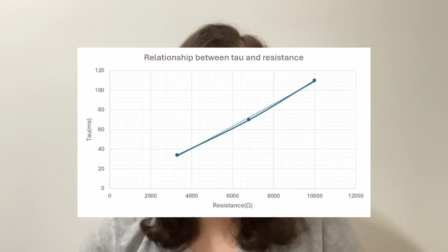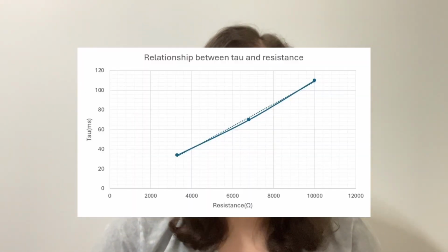This experiment effectively demonstrated the behavior of an RC circuit. The waveforms on the oscilloscope match the expected exponential charging behavior and show how resistance affects charging rate. The measured and calculated value of the time constant show that it's directly proportional to the resistance, and the slope of the graph relating these terms is about 10 microfarad, matching the capacitance. The average error was found to be only 5.32%, confirming the experiment's reliability.